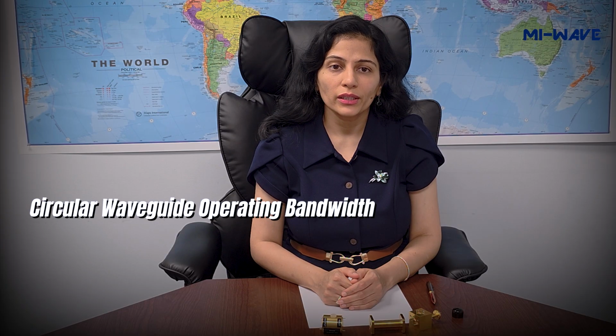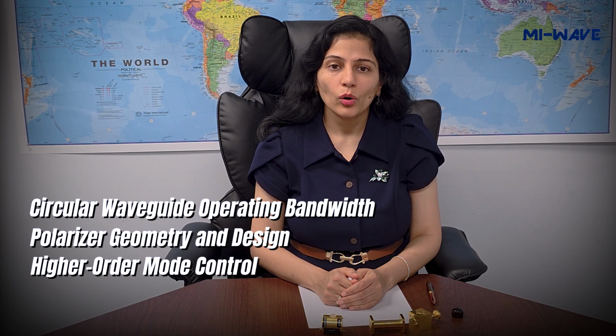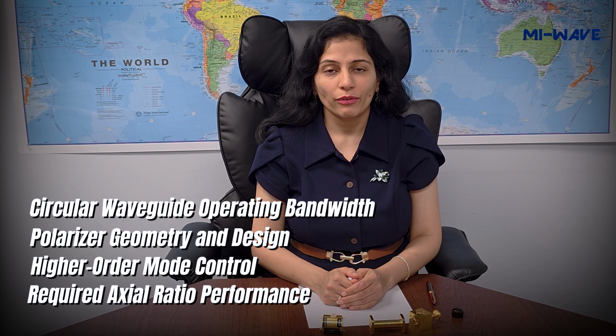Therefore, the usable bandwidth of a polarizer is limited by circular waveguide operating bandwidth, polarizer geometry and design, higher order mode control, and required axial ratio performance. Because of these limitations, polarizers are typically designed for specific frequency bands rather than extremely wideband operation.